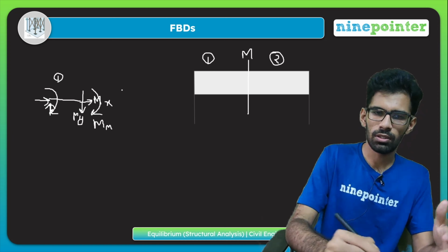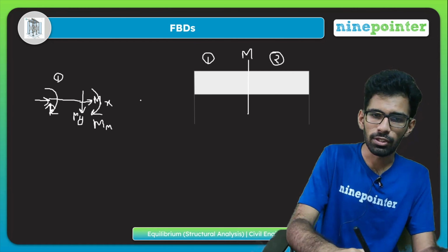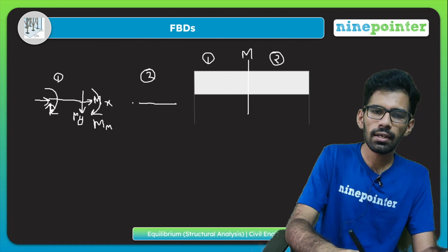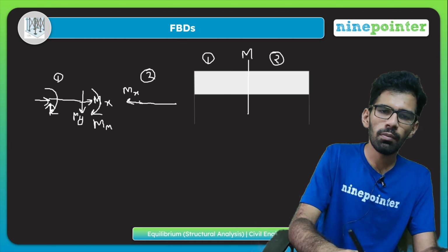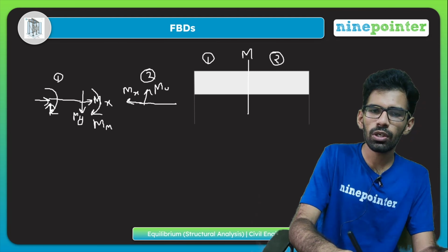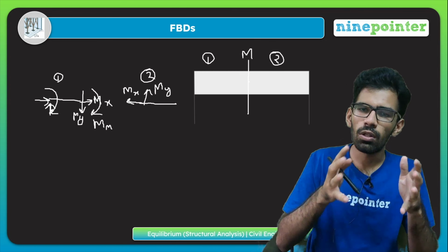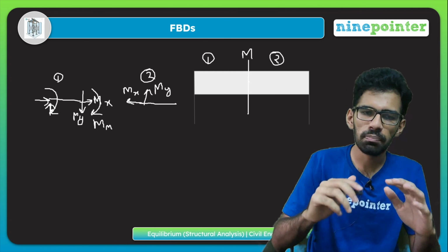It will be similar, most likely the mirror image will be the second part. Okay, and here we have to keep in mind that we draw just the opposite forces because they will be equal in magnitude. Why will they be equal? Because at that joint there is no movement, so all the axial, normal forces and the moments must be 0.